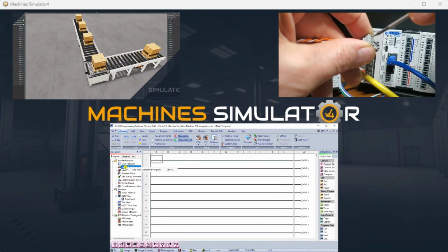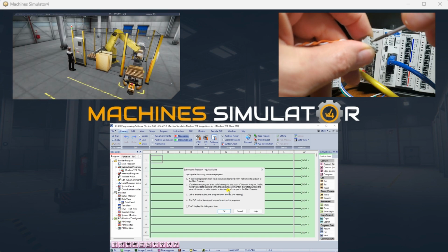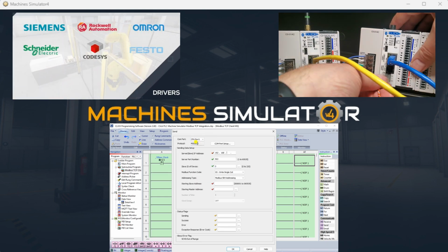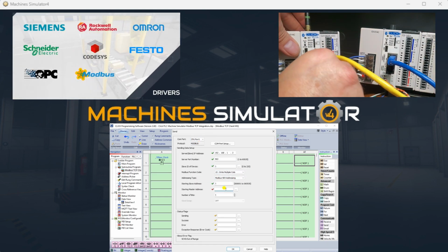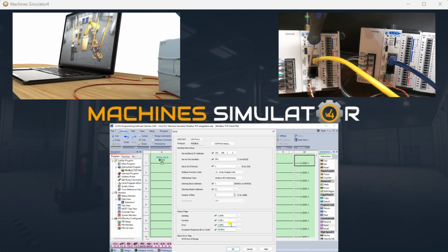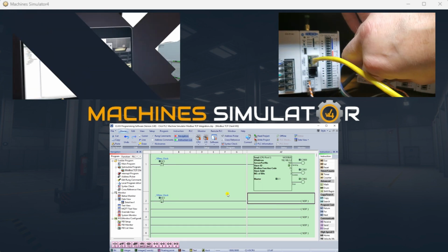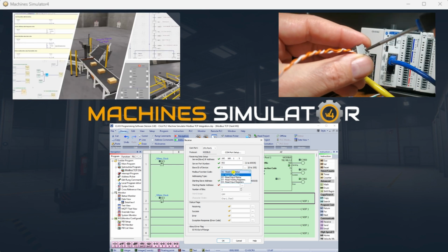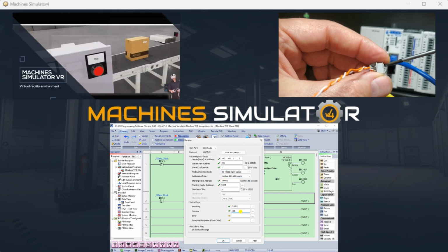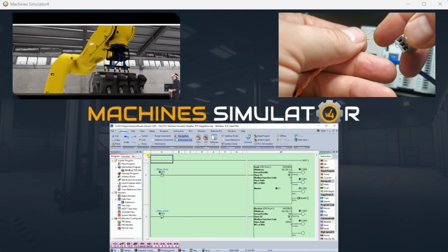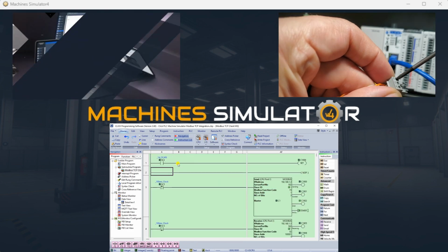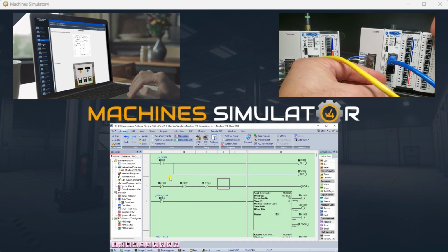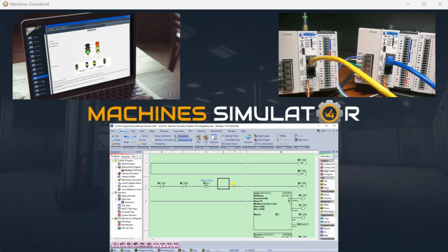Click PLCs have been a long staple for automation engineers, offering a reliable and user-friendly solution for various control processes. However, integrating Click PLCs with Machine Simulator unlocks a whole new level of potential. This post will explore the benefits and methodologies of unlocking Click PLC and Machine Simulator integration. We will be using the Machine Simulator's test conveyor example. This practical example will utilize the Click PLC Modbus TCP communications to the simulator Modbus Server driver.